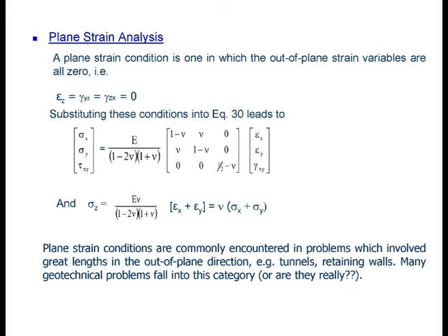Similarly, when you dig a trench, I can't see a machine so fast that can just lift up the whole piece of ground and then leave you with a trench. You cannot. So basically, the guy is digging, and at the tunnel heading, there's always a three-dimensional stress state occurring. So there's something that we need to be a bit more mindful about. That even in a problem that looks like it is plane strain, very often it's not fully plane strain. But if you use it in a knowledgeable way, it's okay.